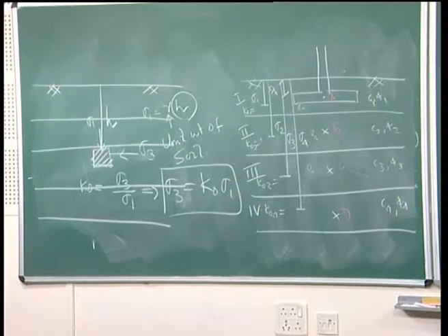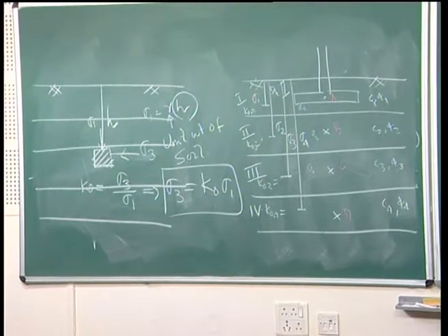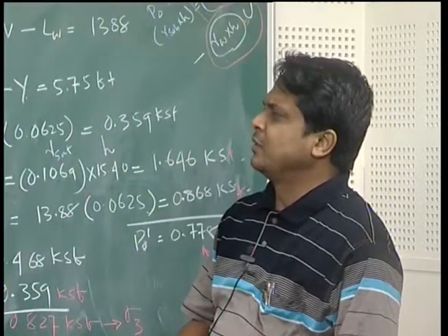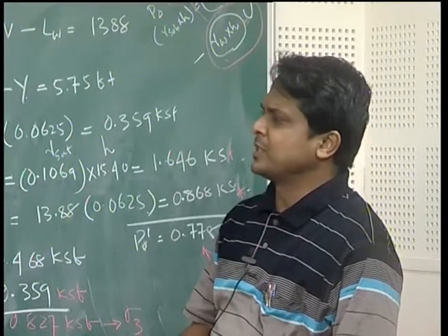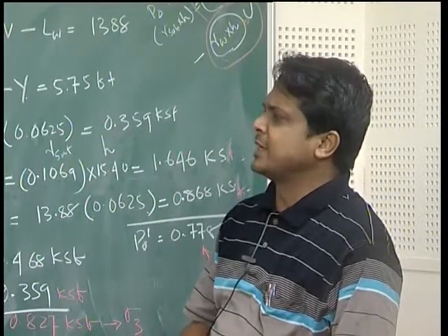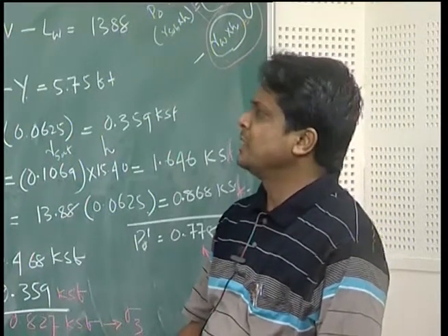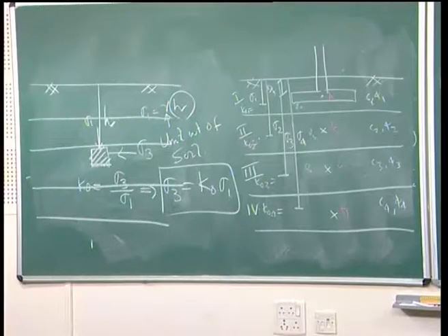So these are the two methods: hydraulic fracture as well as pressure meter method. Generally in India, the pressure meter method is widely used, but the hydraulic fracture method is used where rock mass is there, because you cannot do the pressure meter test in rock mass.